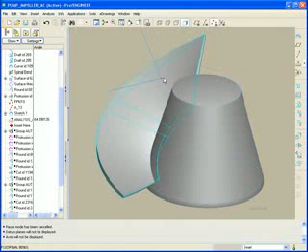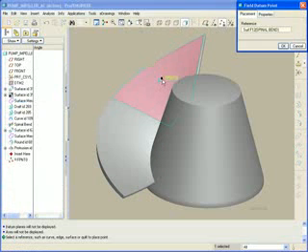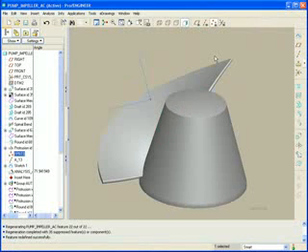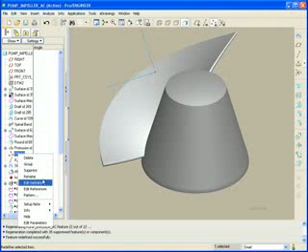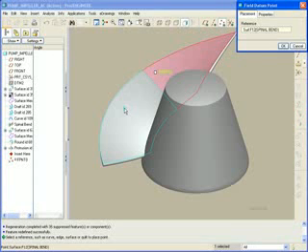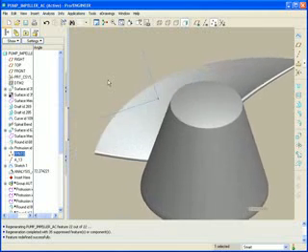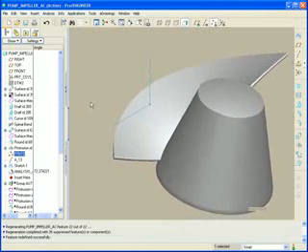This field point thing? Well, if I pick the field point, and I'll do that here, edit its definition, I can drag this point and put it in a different place. When I call this OK, you'll notice that the angle analysis completely updated. I can pick that same field point, edit its definition, and move it onto a different surface. And you'll notice again, all the subsequent features updated as well as the angle.